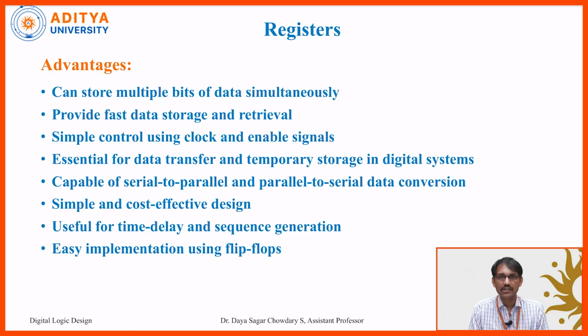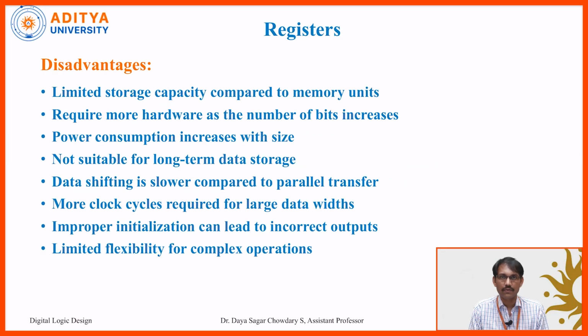Most of the time we want shift registers, because in order to shift the data from one place to another place, these circuits are used in the architecture of CPUs and GPUs. Also capable of serial to parallel and parallel to serial data conversion, because this is the advantage of the shift register. And simple and cost effective design, because the construction is very simple, depending on the flip-flop stages only. Useful for time delay and sequence generation, with easy implementation using flip-flops.